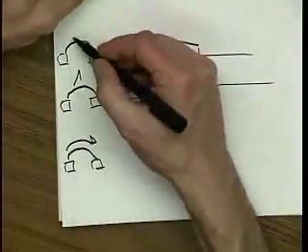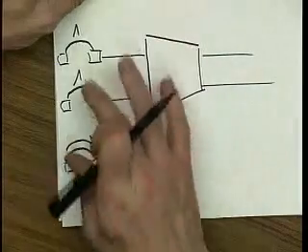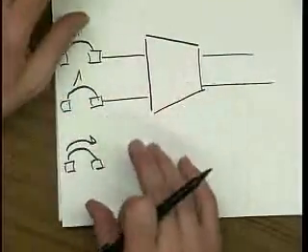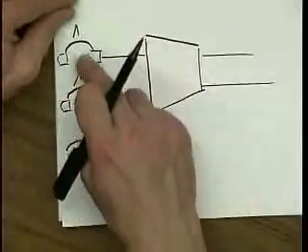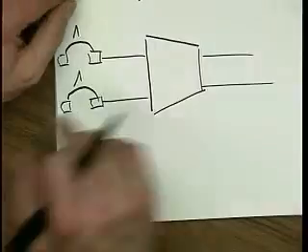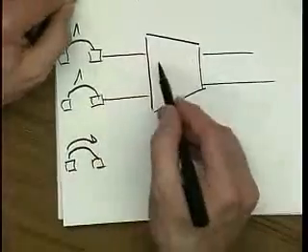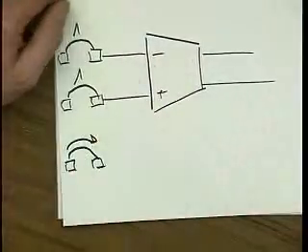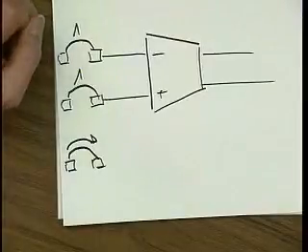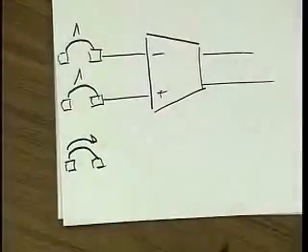But if we have a fully differential circuit, and the wires are arranged strategically, then approximately the same spike appears in both wires. And if the amplifier only looks at the difference of these, then that signal is rejected. Right? The same thing also applies at the output.